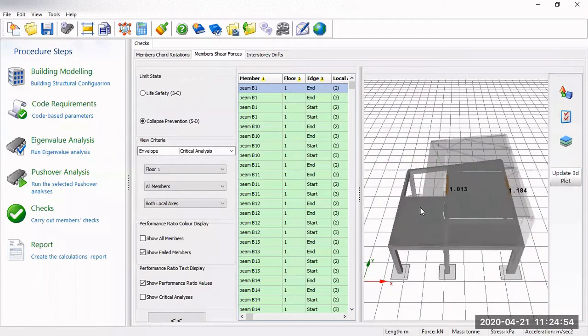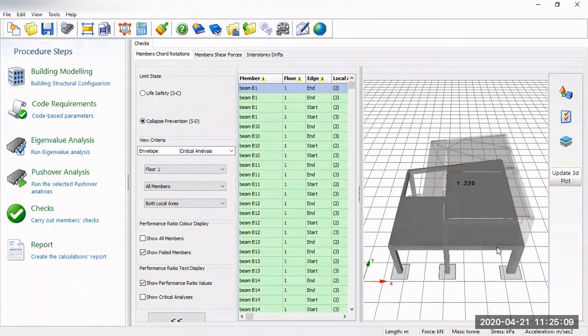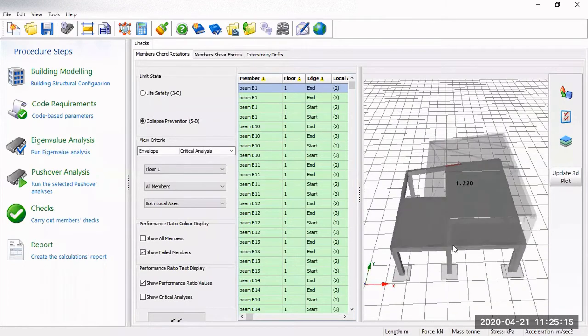Which is this stage 1 here. I have successfully identified which of the beam elements are critical. Like for member shear force, we realized that these 2 beams are critical, and member core rotations, basically these shear walls, and also maybe I will consider this strengthening of this column as well. All right, so now I complete the stage 1 already.